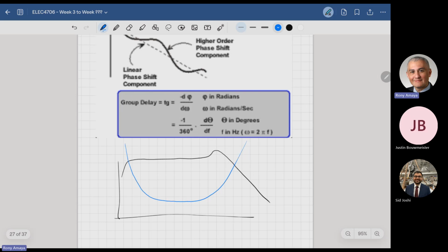Okay. And now the problem is, if you then take the 3 dB point as being here, look what's happened to the group delay. And this is just gain. It's really a conflict between the amount of group delay and the deltas of group delay that you're permitted to work with. So you get more bandwidth, you get more group delay,